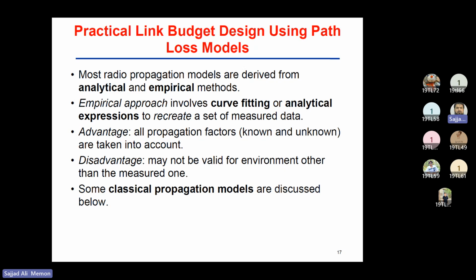If it is less than or equal to the minimum receiving power, then we either increase the transmitting power, which is a very basic way to adjust for the losses, so that the received power is increased, or we try to improve the channel quality by reducing the losses that are in our hands, like filter losses, transmission line losses, and other losses that we can reduce. Either way, the received power should be greater than the minimum power requirement of the receiving antenna.